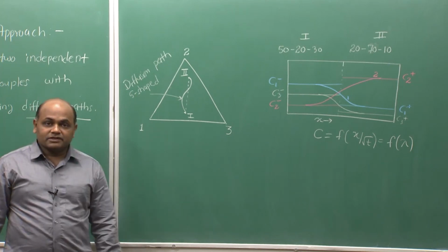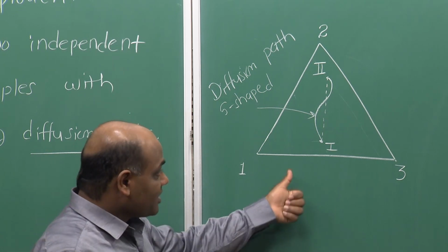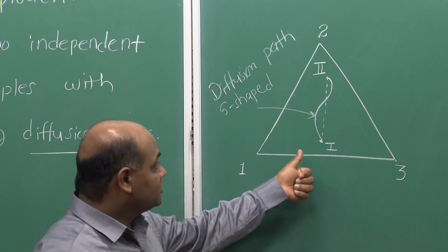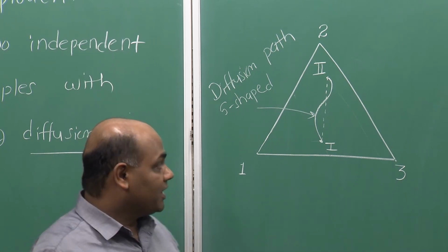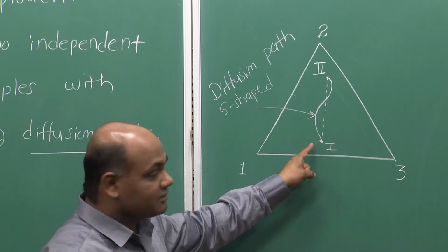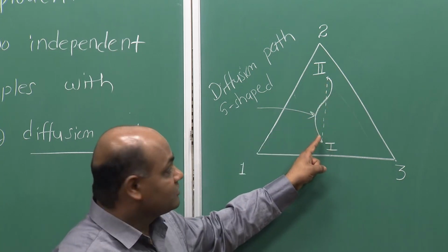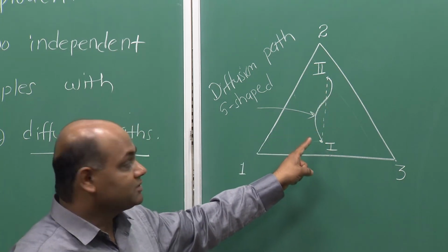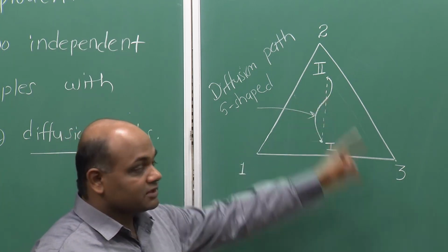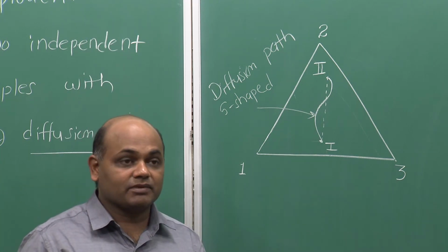When we conduct the diffusion couple experiments, in order to assess the reliability of our experiment, we should usually prepare at least one diffusion couple at 3-4 different times, the same couple, that is the couple between the same two terminal alloys annealed for 3-4 different times. I have to make sure that at different times the diffusion paths are the same. So, that helps to establish the reliability of the experiments.